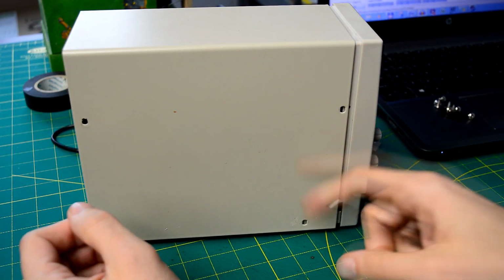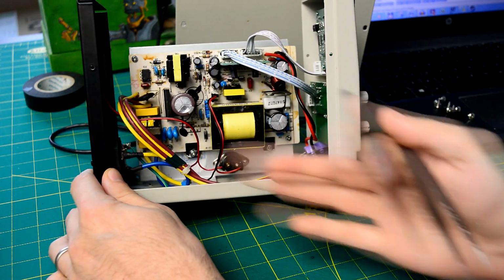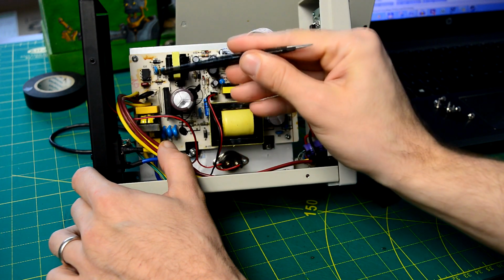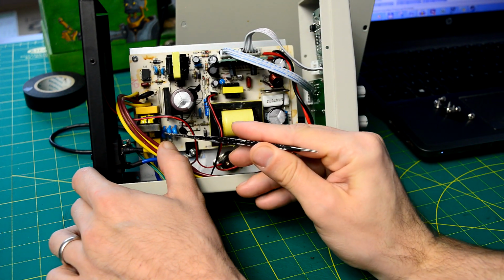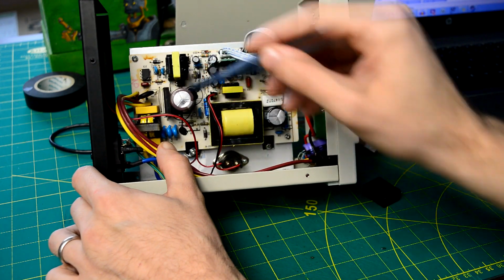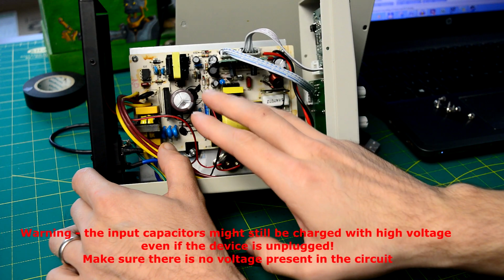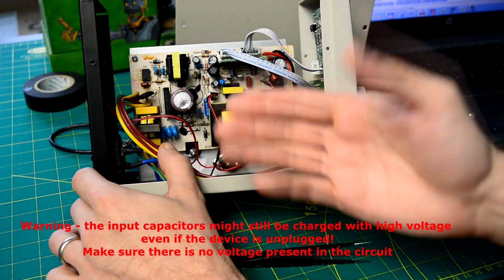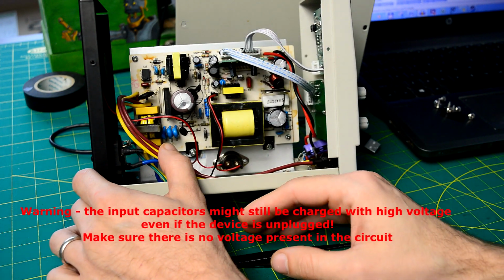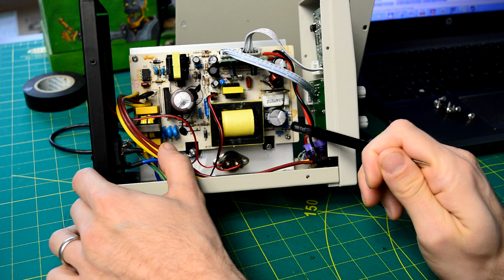Now let's have a look at what's inside this thing. So basically this is the circuit. It's not very complicated. So on the left side you've got your input mains power circuitry, input filter, input capacitors, rectifying bridge, and so on. So don't mess with this area since this works with high voltages, and of course only open the device if it's unplugged, so be safe about things. Then you got your transformer and then your secondary side.